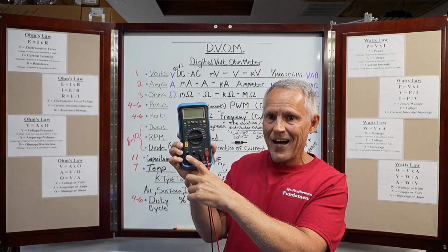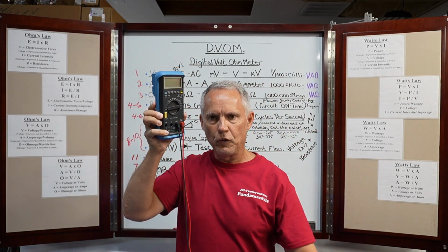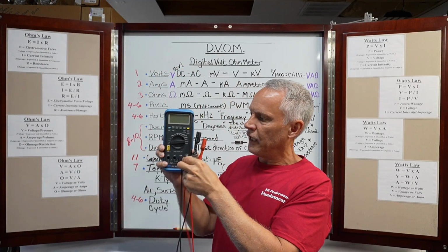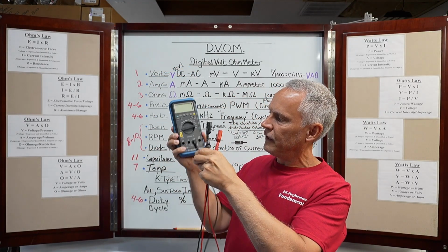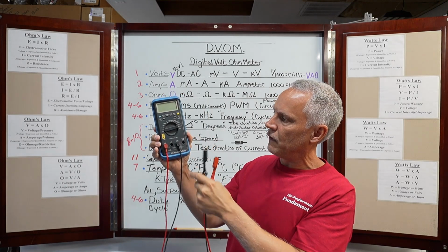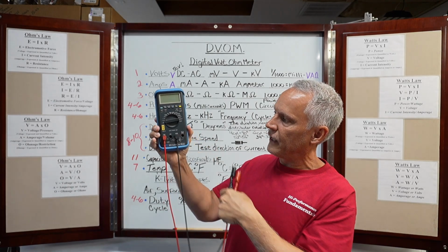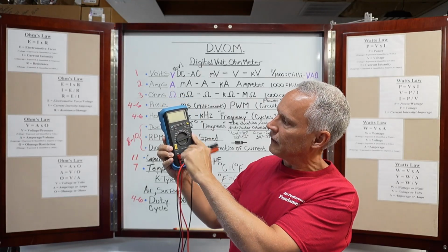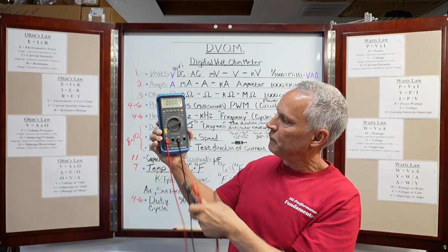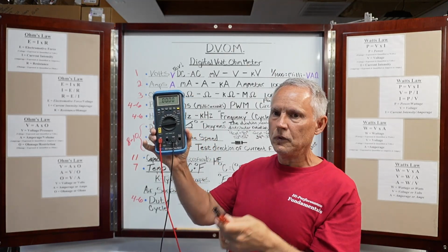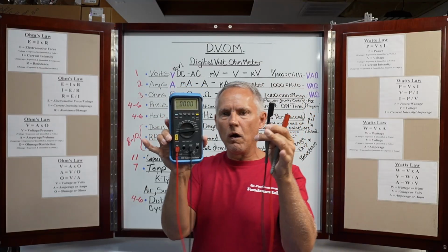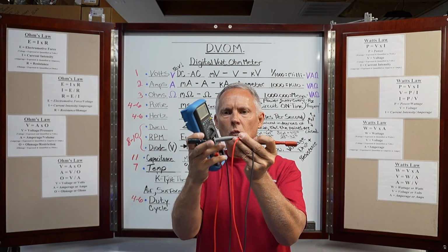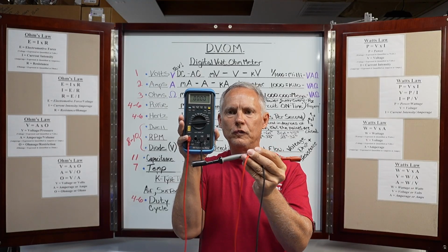So this is an inline also, just like the other one I showed you. You will literally wire inline, just like this. So you'll take your red or your positive lead, stick it onto your 20 amp scale, keep your ground lead or your negative lead on your ground terminal, or what they call common, right? And select over here. We'll go over and select 20 amps, right? Now our meter is an inline ammeter with a fused circuit, just like the other one was.